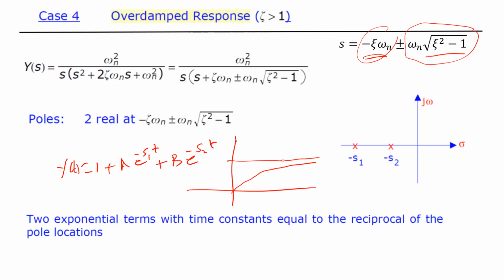If you remember in the last lecture, at the beginning of the lecture, I said we will be covering the idea of dominant poles. What we are going to study in this course, we will be studying higher order systems. However, the dominant poles are of the second order. So we ignore the others and approximate those higher order systems by the effect of the dominant poles.